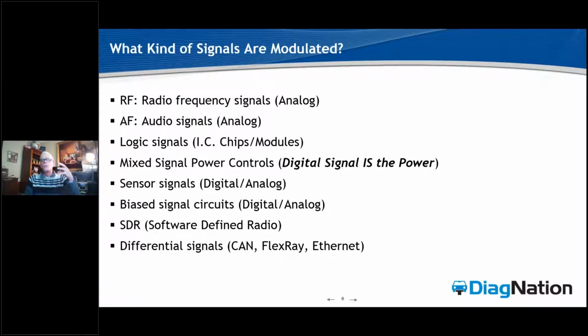So we're also modulating audio signals, obviously, right? We've got dings, beeps, chimes, radios, music, human voice, audio, all of that integrated into the car. We have to be able to understand how that's modulated. And I'll tell you this, my experience running the DiagNation support is that more and more technicians are having to get themselves involved in AC current frequency, audio frequency and radio frequency diagnosis and understanding.